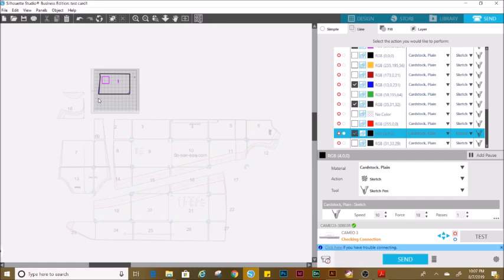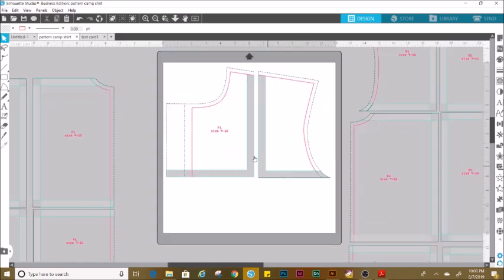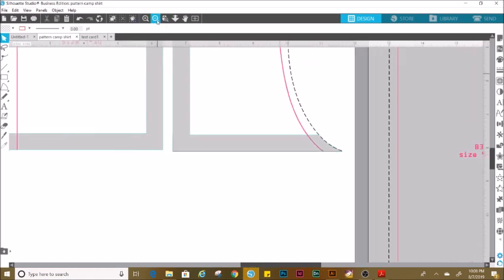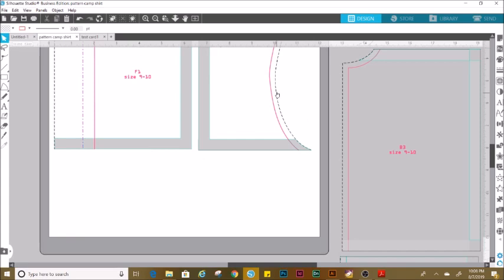Because on this one right here, when I was doing my pattern, I actually, like the way this was, it didn't have any lines down at the bottom when it connected, because you cut it out. I went in here and I actually added the lines at the bottom by hitting the line, connecting it here, shifting it all the way over, and drawing the line there, so that way it could have a full cutout when it cut out.